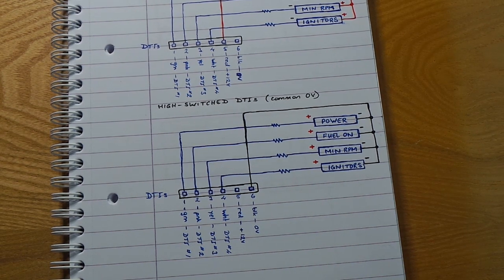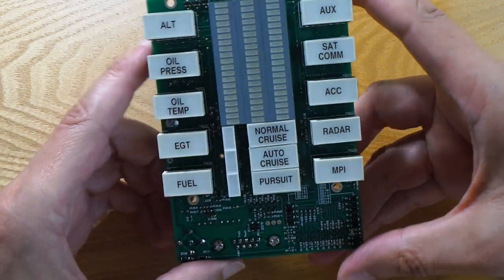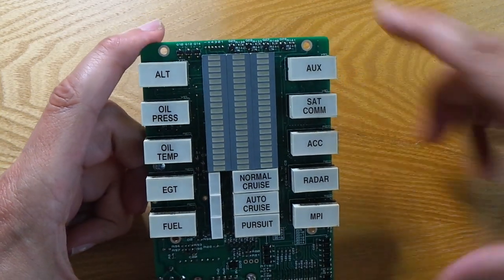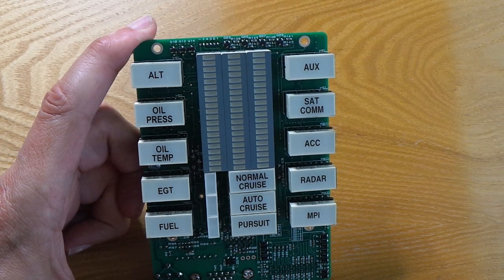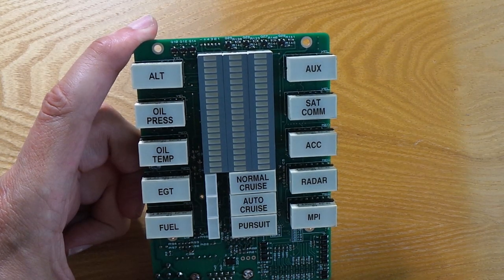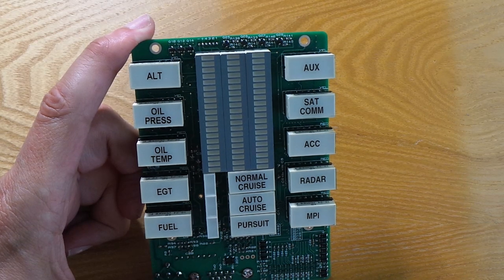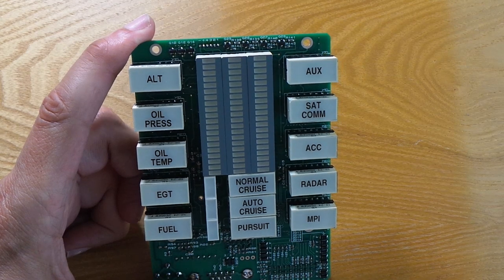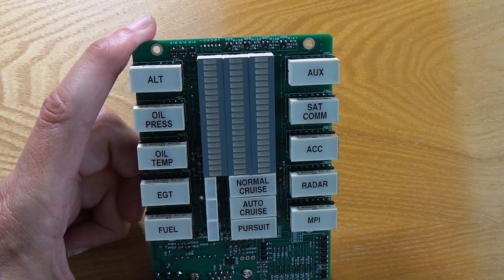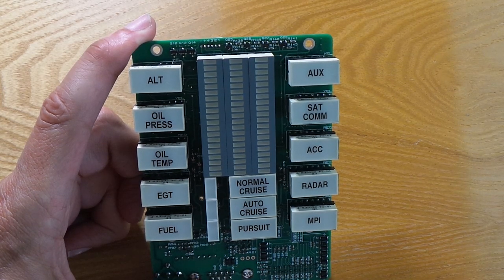Let's just say a quick word about some of the other user options on the unit. We've mentioned the dash top indicator polarity, which can be changed over. The way that we do that is we hold switch number 1 in the active position, and then we give a long press on push button number 1. That will enable the dash top indicator polarity to be changed over.